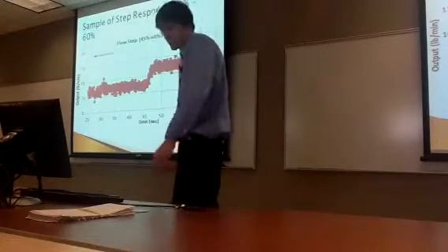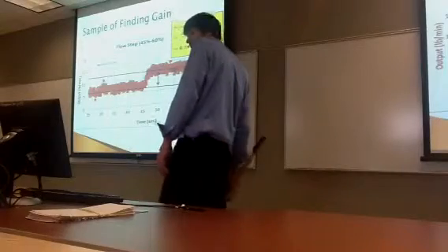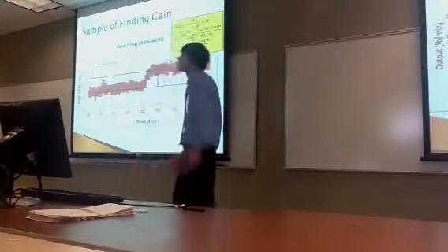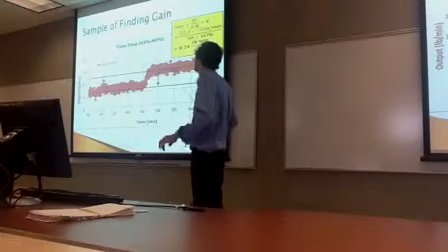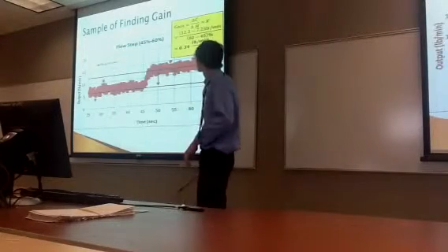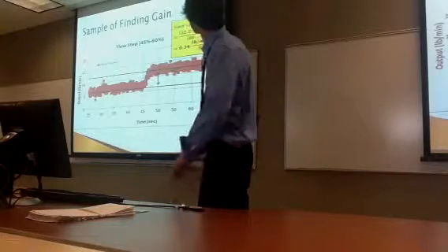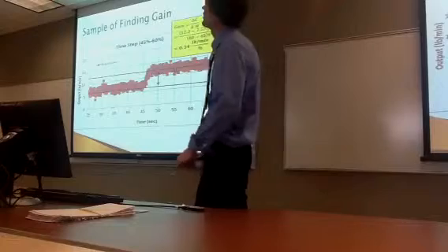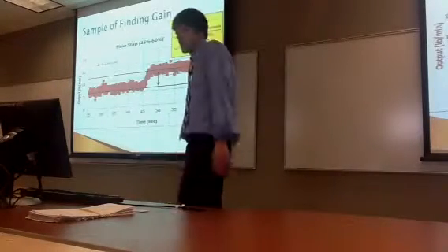The next step we took was to find the change of C, which is the change of the output. We did this by finding the longest range of steady state, taking the average of that, and then plotting a line for that average to find your change in C. In this part, we found that the gain, which is change of C over the change of the input, is 0.34 pounds per minute per percent.